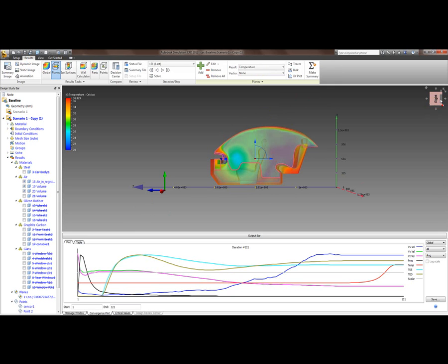So I now want to see whether it's met our goal of uniform cooling. As you can see, it comes in. If it's hot in the cabin, I want the airflow to come through and evenly distribute, to keep it to a decent and comfortable temperature. First of all, I'm going to plot a graph. By doing this, I just want to plot a few areas and see the change in temperature throughout that zone.